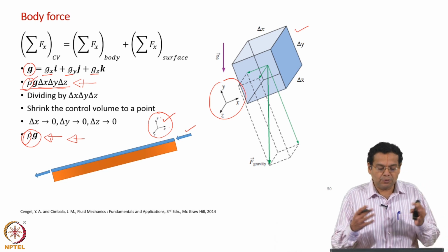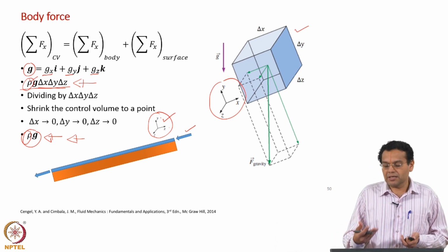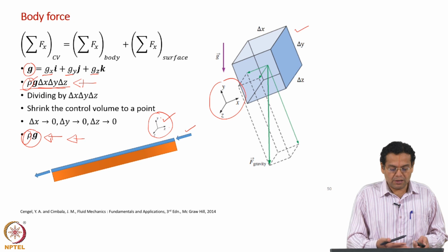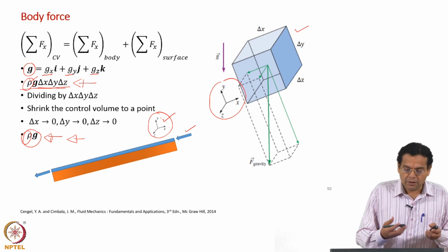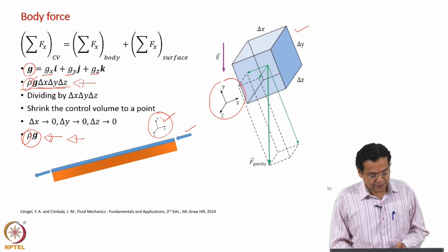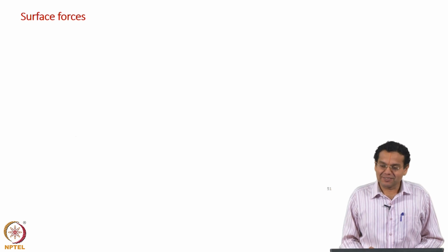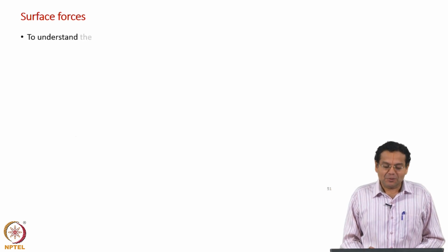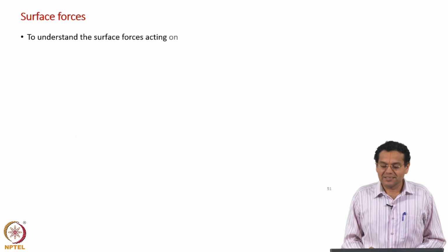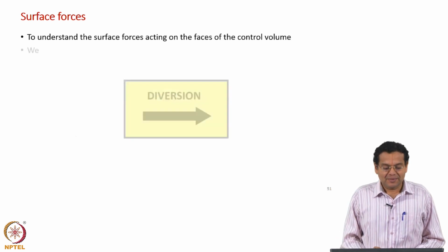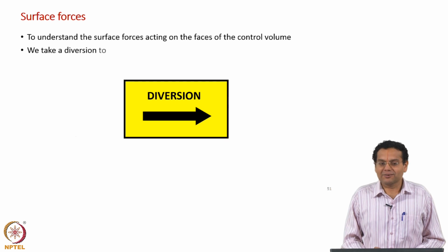Of course, once we pool all the terms, we look at the significance of each term there, but as we go along we should also be familiar that all the terms are on a per unit volume basis. Surface forces are all the more involved, and hence we pay special emphasis to that. To understand the surface forces acting on the faces of the control volume, we take a diversion to solid mechanics.